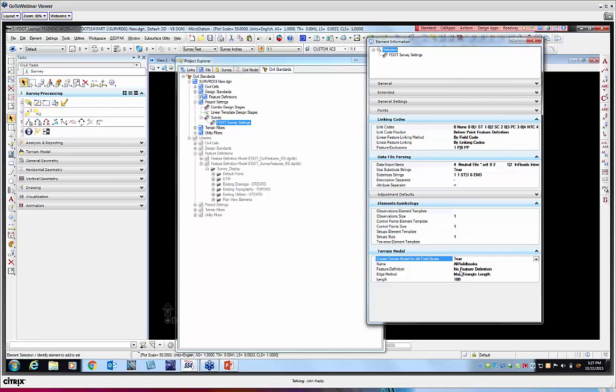So what Bentley has done is they have set some specific defaults for files that don't have this type of attributes attached. So they'll go ahead and set these settings to their default, and the default is true. I think the maximum triangle length is set to something like 1000, so these settings are really not very good for using in the default state.